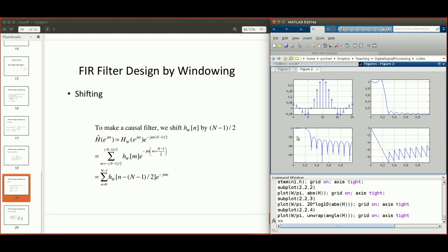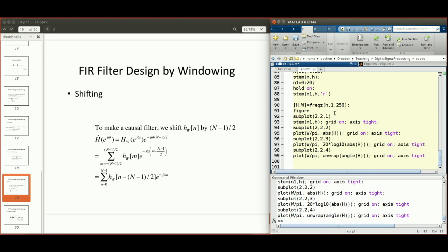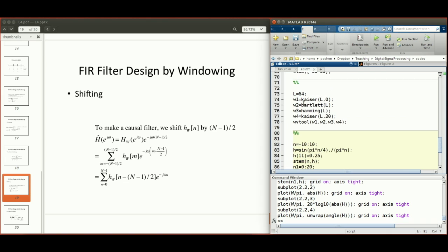And if you plot it on a log scale, the horizontal axis is still normalized frequency, but the vertical axis becomes dB. Then it's gonna look like that. You have a pretty flat passband, and then the stop band amplitude is a lot smaller. And this is indeed telling you that it's a linear phase in the passband. That's the effect of using the first window, the first kind of window, W1.